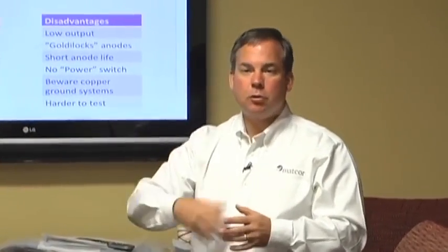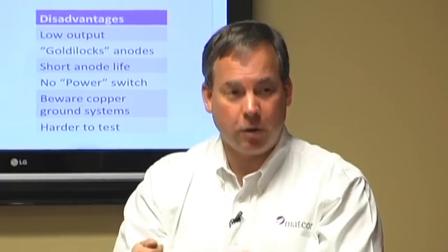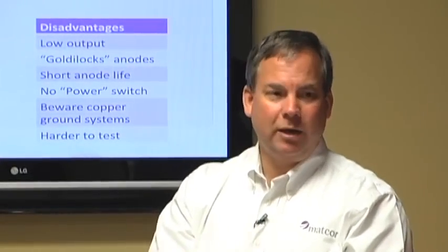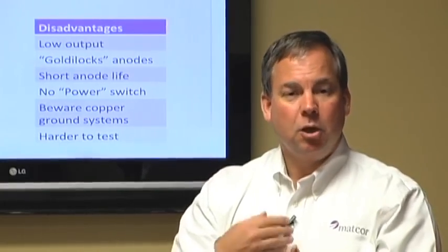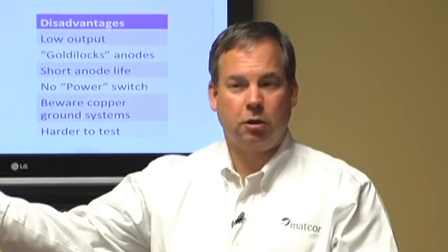Often they do it through a test station, so you can actually measure how much current's flowing off it. That's the only really way to know if the anode's still working or not. Right. Well, it's not the only way to know. It's the easiest way to know. It's also the easiest way to estimate how long the anode life will be, because we know how much the magnesium will consume for every amp of current discharged off it.